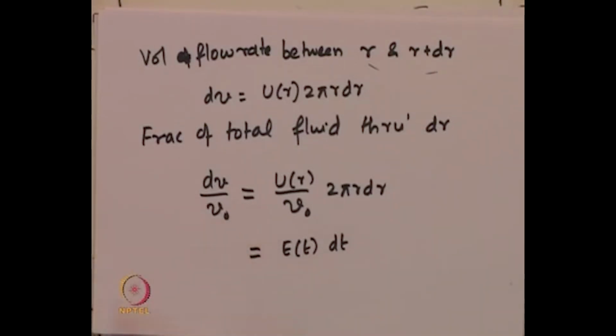So, what we have seen so far in this lecture is essentially different properties of the residence time distribution, which is the mean. We have looked at the variance and the skewness, and then we moved on to the residence time distribution of the ideal reactors.